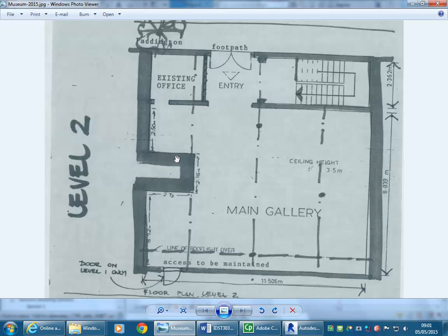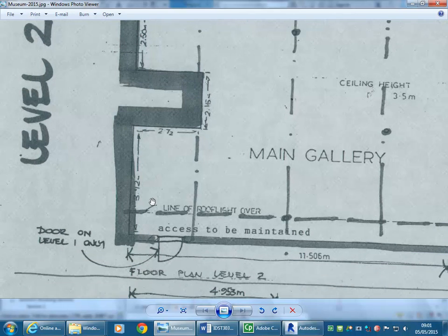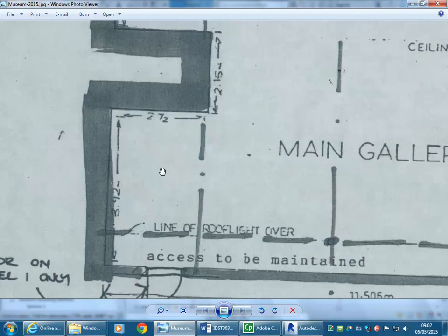And then you can see you have this area here that may be a courtyard, or it might just be a void, where we have these extra walls that we'll need to add. And you can use reference planes to do that, as I've done previously, but I just want to show you, you can do it simply using walls. You don't always need to use reference planes. They're just an aid to help you, and they're not necessary to set out accurate measurements.